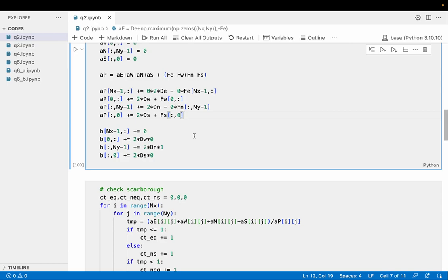Now coming to your source terms, they will get added as and when you have Dirichlet conditions. So you have a Dirichlet condition on the bottom boundary and on the top boundary. On the bottom boundary the value is T equals 0, so you just multiply that coefficient with 0, and on the top boundary you have a coefficient of 1. And since these flow coefficients are 0, I have not added those terms here.